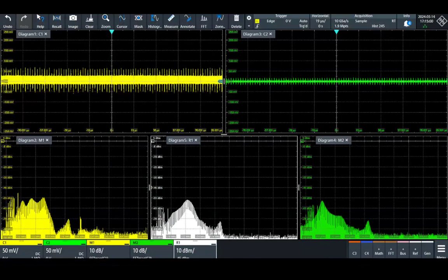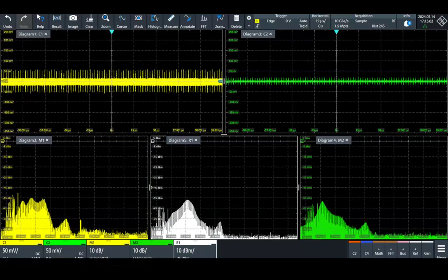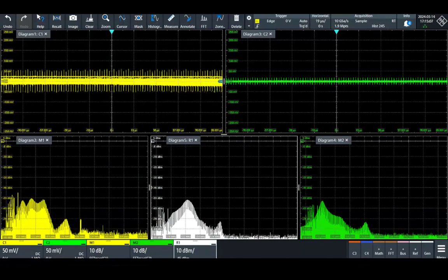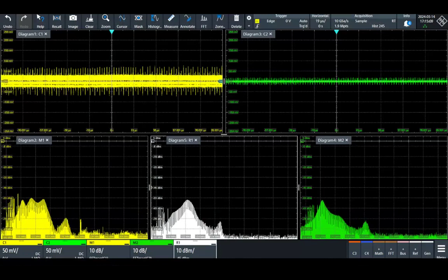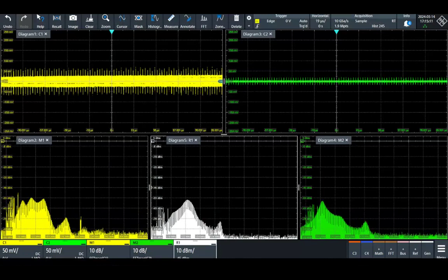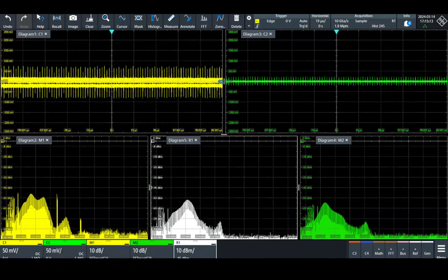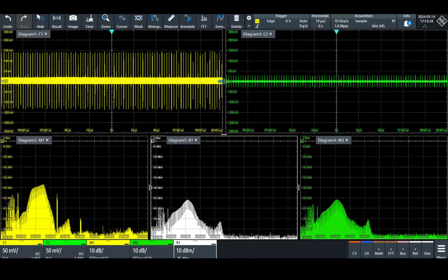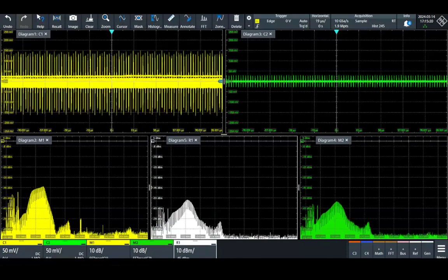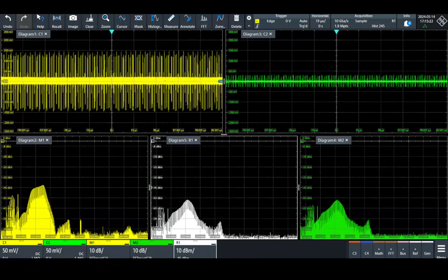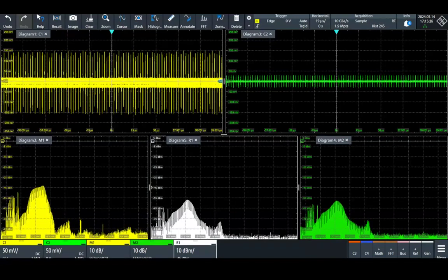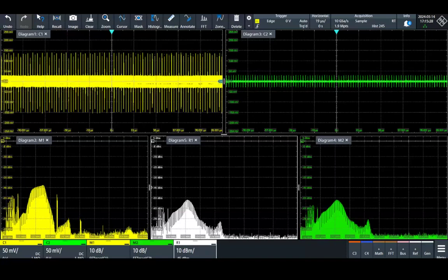Now, if I introduce the jumper more and more, the parasitic inductance around this ferrite is changing. Look at where the peak in the green trace is. When I am introducing it, you see that the peak is going to the right. This is because the inductive effect of the jumper is very important. They are, I don't know, 5, 6, 10 nanohenries. But with these 5, 6, 10 nanohenries, I have the possibility to do some kind of tuning of the LC